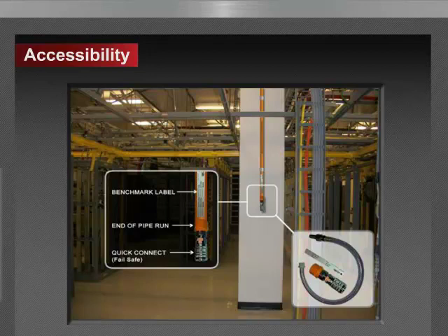Yeah, so different models and different manufacturers have different communication methods for Modbus and BACnet. There are various models of detectors on the market that do have that capability, and then there are third-party interfaces, or black boxes, if you would, that will take the open protocol from various manufacturers' panels or detectors, and bring them into their black box where they'll do the Modbus BACnet conversion.